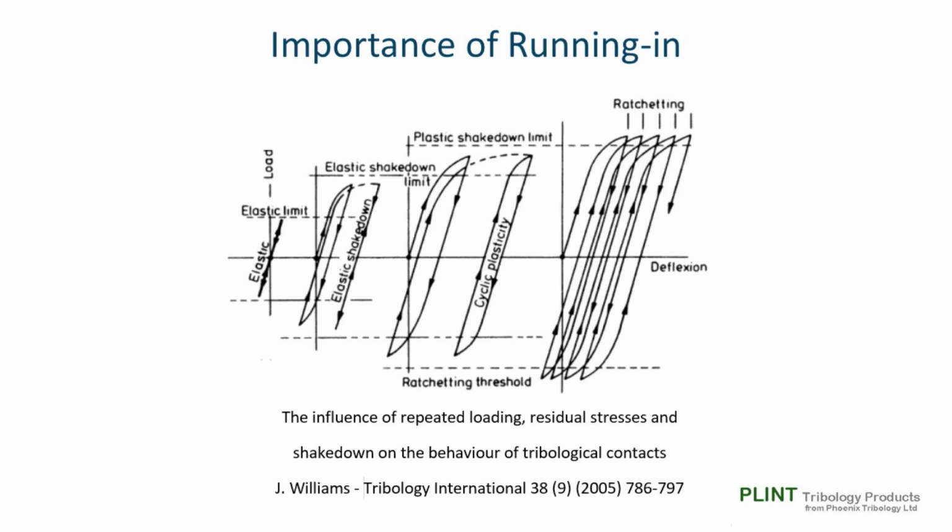Residual stresses are stresses that remain in the material even when the external load is removed. After shakedown, the load experienced by the material is subjected to both contact stresses and the residual stresses introduced during the shakedown process.